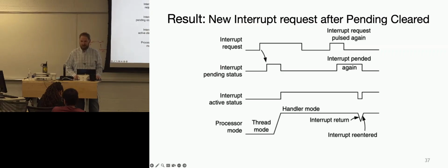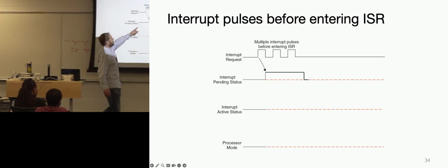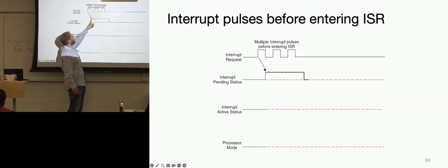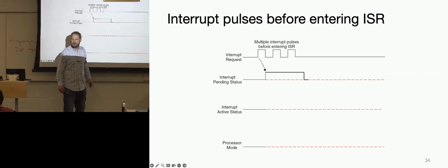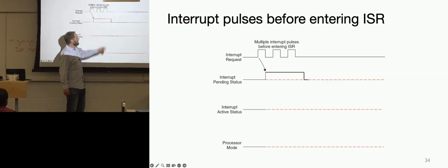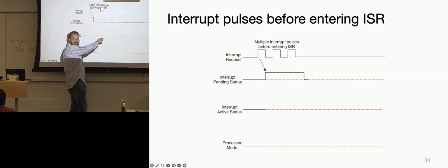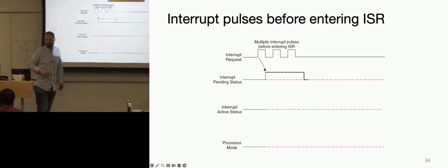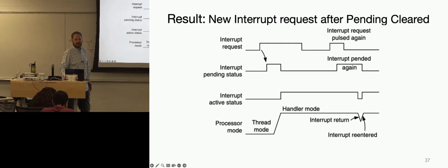The example for slide 55 where there are multiple pulses. Yes, there's no state holding information there. It's already high. We never got out of pending. So pending was set here. Pending could have been set here, could have been set here, but pending never went low. It kept overlapping. In the example we're showing now, pending goes down early and you go into active, and then pending's reset. But in the other one, pending was never taken out of pending. Pending was always asserted, so it just kept on being asserted over and over again. Okay, I got you on the trick question that you couldn't answer.